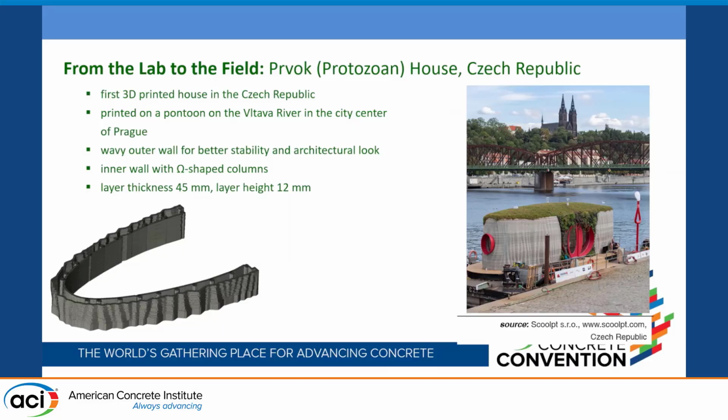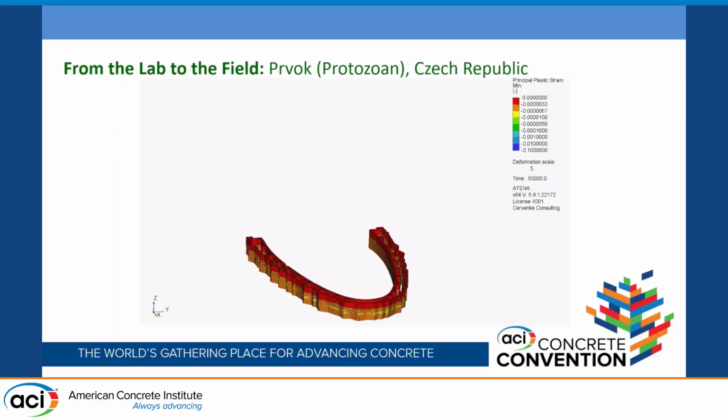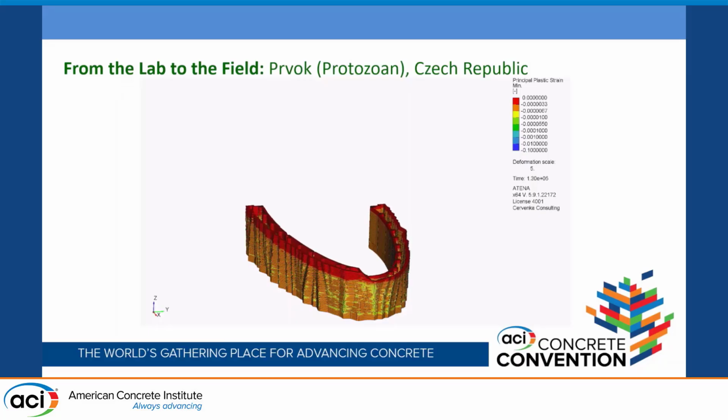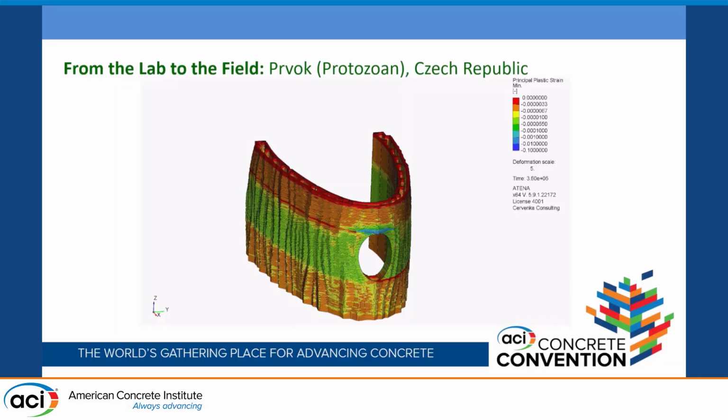So now I want to go to a little bit bigger structure. We simulated this structure, which was a kind of simple 3D printed building. They also printed it and tested the strength of it in the laboratory. Actually, the loading machine was not so big, so we just checked that they cannot break it, so that it is strong enough. So there are no really very good data for this. But anyway, we just use it to present that we can model this 3D printing process directly from the G-code. So this model you see is very irregular, really created from the G-code directly, and the G-code drives the model development as well as the activation of the finite elements during the simulation.